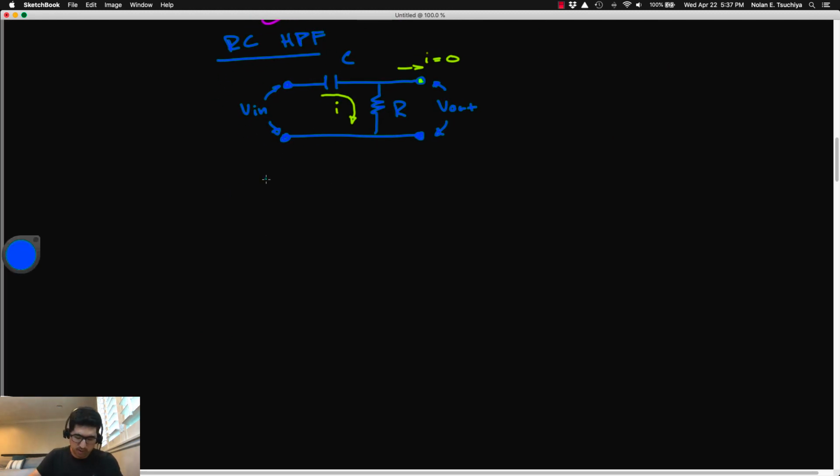Okay, so one thing we might do is start with the capacitance law that says all the current that passes through the capacitor C is equal to the capacitance C times the time derivative of the voltage drop across it. So our first equation is going to come from, maybe I is a poor choice of terminology. We'll say our first equation will be I is equal to C dV/dt. This is just the fundamental rule for a capacitor.